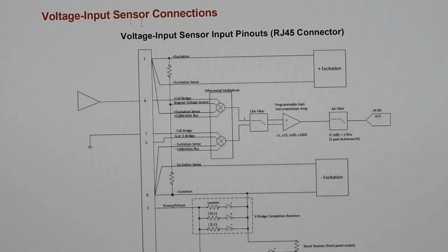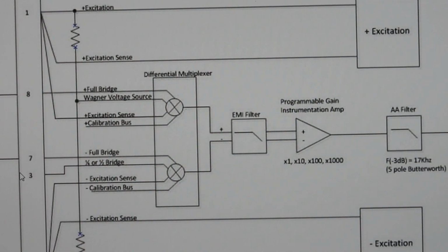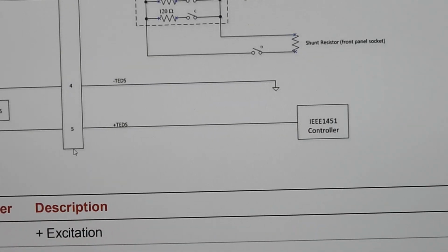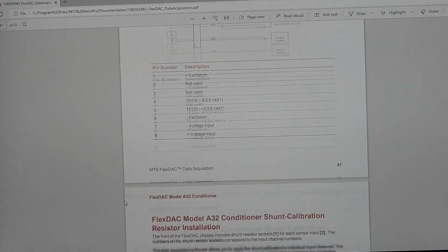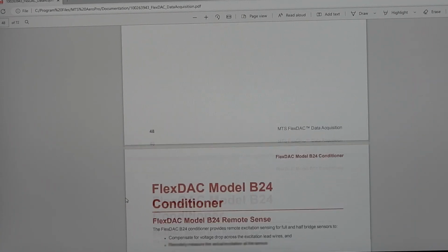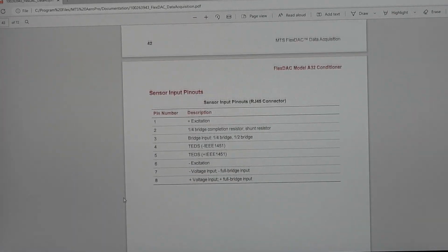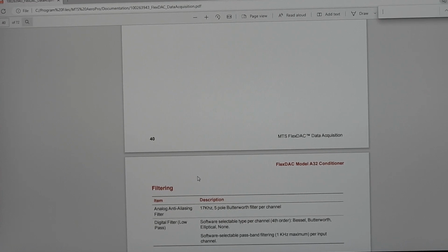And then if you're doing just voltage connections, we're looking at input on 8, and then ground and common on 7. I think that's got an LVDT. It should, yep. It needs to put some power out to it. Maybe the full name, linear variable differential transformer.